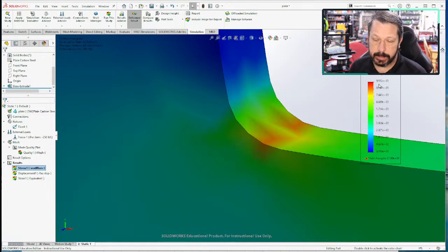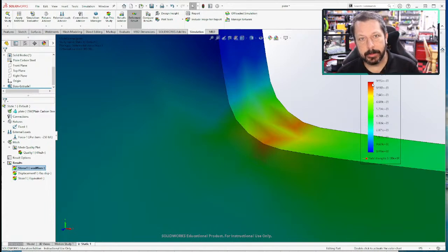So usually when you're looking at your highest stresses in a finite element simulation, unless you have gone through a long, tedious process of really optimizing your mesh, then that number is probably unrealistically high and being controlled by some little singularity type thing, some point on this mesh.